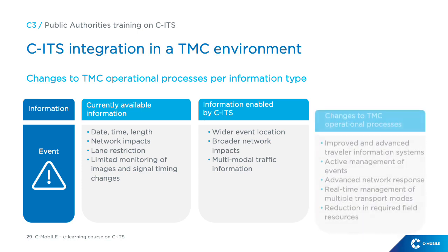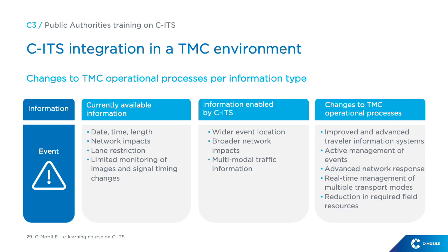The changes to the TMC operational processes comprise improved and advanced traveller information to support area accessibility during events, proactive management of events, advanced modelling of network response to traffic alterations, enabling predictive traffic management of network analysis, real-time management of multiple transport modes and mode shifting support, and reduction in required field resources to support events traffic management.